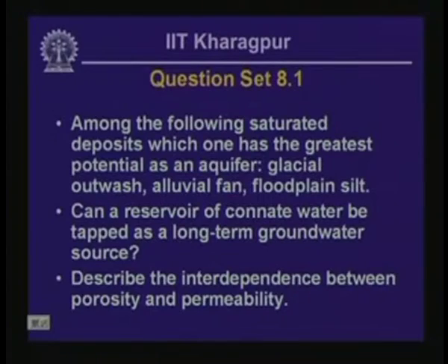If you start tapping connate water, it is not going to last over a very long time before depletion, and because the pore space in which connate water is stored is isolated, it does not really have much option of getting recharged during wet seasons. So connate water therefore does not qualify as a groundwater source to be used over a relatively longer duration.